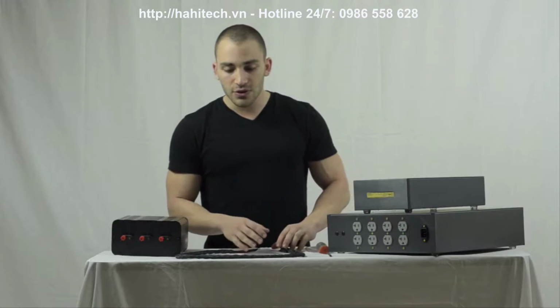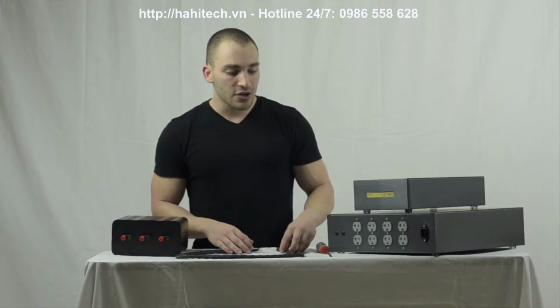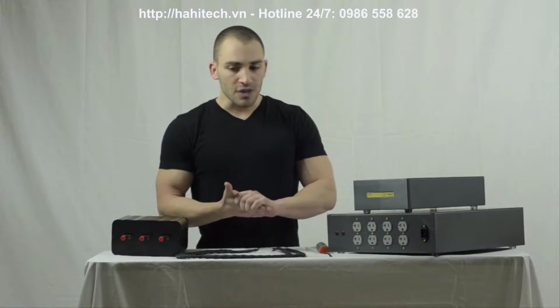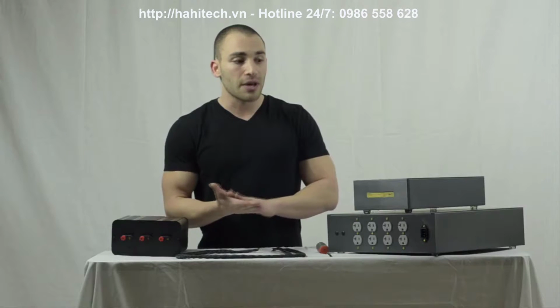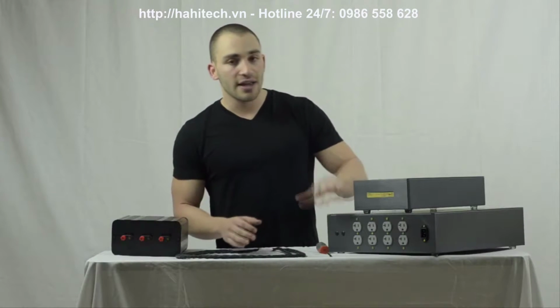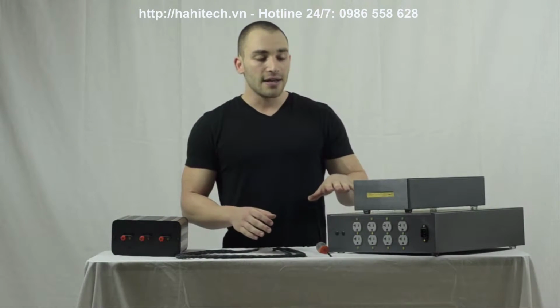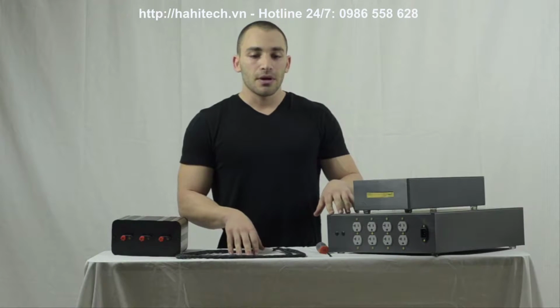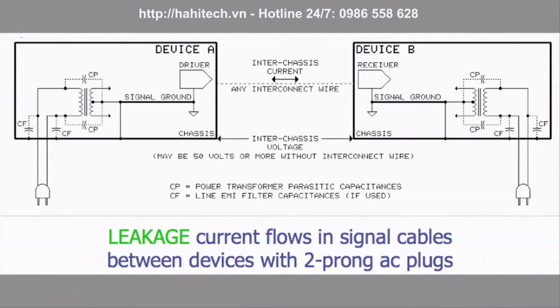One of the other things that you see in a lot of audio systems, and for whatever reason a lot of audio dealers will recommend this, is a lot of cheater plugs. People install a cheater plug thinking that it's the IEC earth ground that is causing the ground loop that they're hearing, and they think, okay, if I float the earth ground, I'm no longer going to have a ground loop.